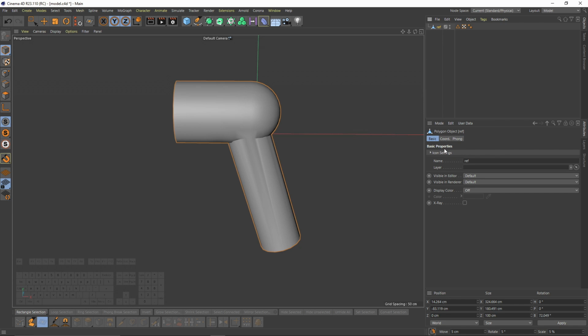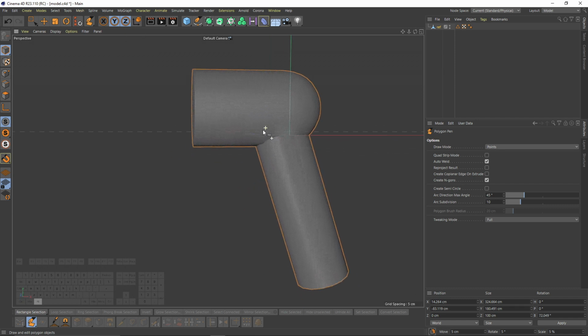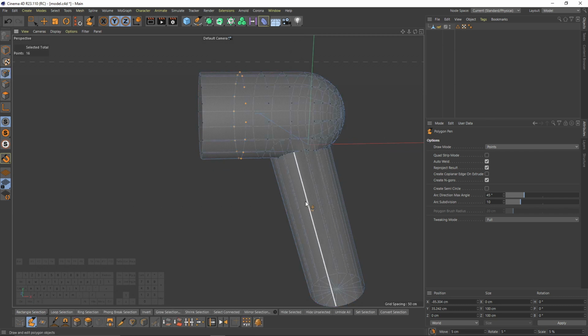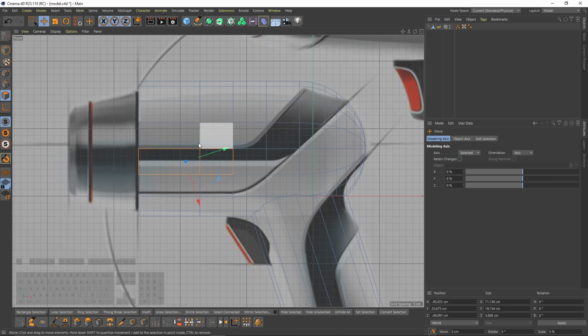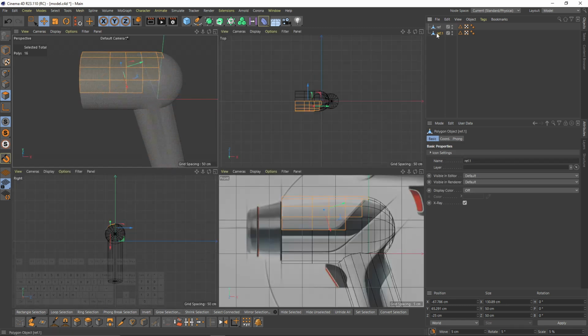So first thing, I will go to my objects, basic properties, and enable X-ray. Then I will go to mesh and select polygon pen and enable reproject result. So let's first look at the mesh, and it looks like I can steal these polygons. So I will select them, then I will right click and split, and I will turn off the X-ray of the new object.